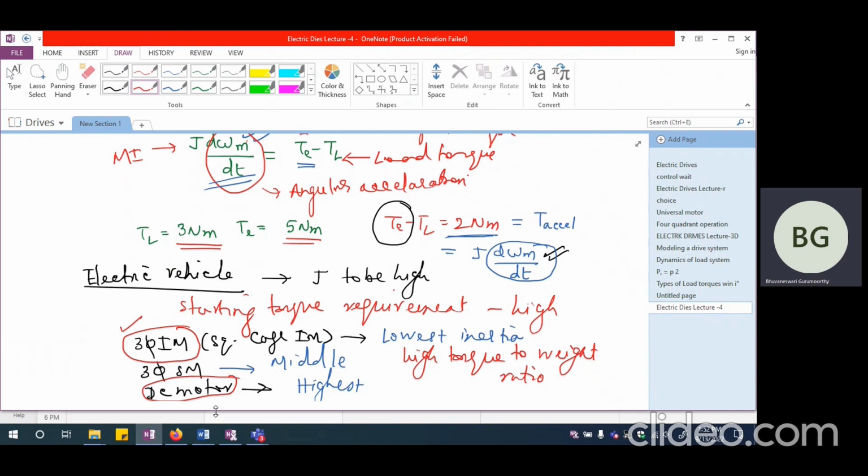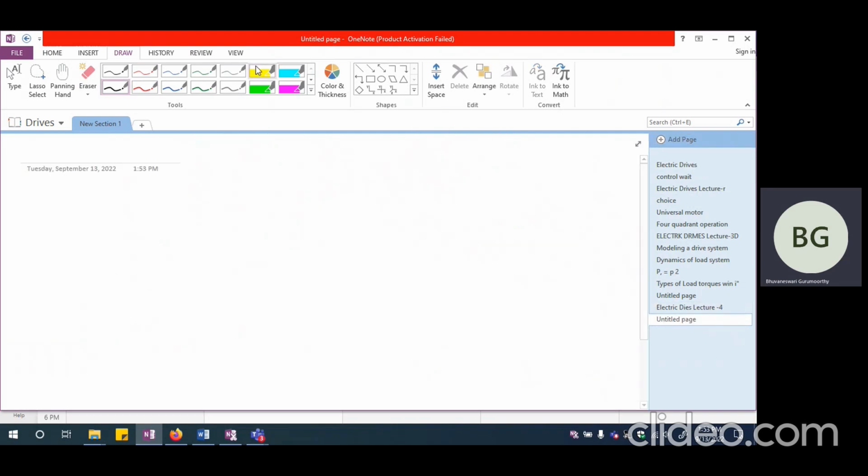In general, if we have the dimensions of the machine, we should be able to calculate the volume it occupies, and depending upon the material used for making the machine, we should be able to calculate its weight. And if I know the weight, I should be able to calculate the moment of inertia as well. But in most cases, we may not have all the dimensions of the machine available. If not, we are not going to be able to calculate the moment of inertia very easily. That is the reason why we should know how to determine the moment of inertia.